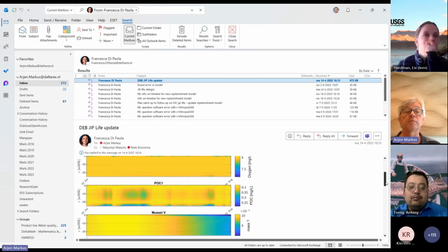This is actually a result from water inside a monopile. We've used Deltares to model that, together with the hydrodynamics being estimated. What you see is the concentration over the length of that monopile in time.